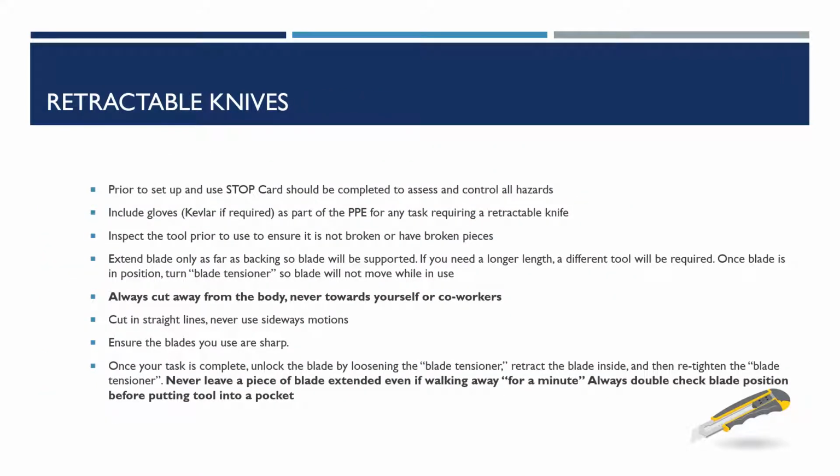Retractable knives. Prior to setup and use, a stop card should be completed to assess and control all hazards. Include gloves as part of the PPE for any task requiring a retractable knife. Inspect the tool prior to use to ensure it is not broken or have broken pieces. Extend the blade only as far as the backing so the blade will be supported. If you need a longer length, a different tool will be required. Once the blade is in position, turn the blade tensioner so the blade will not move while in use.